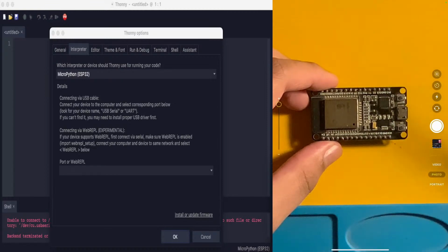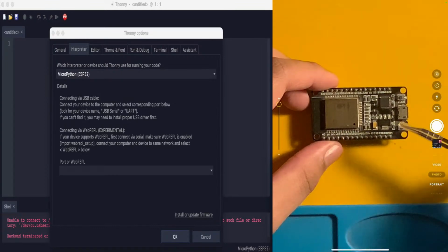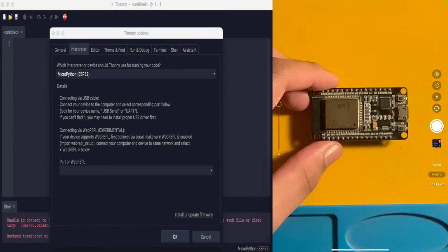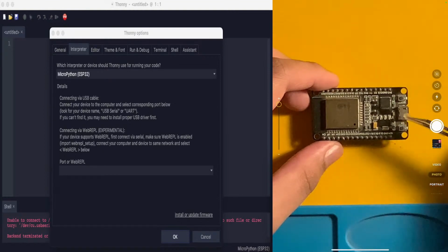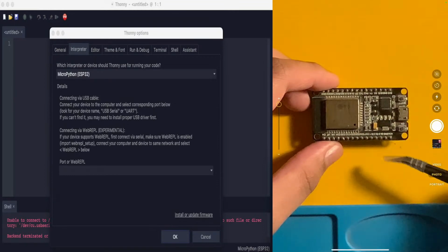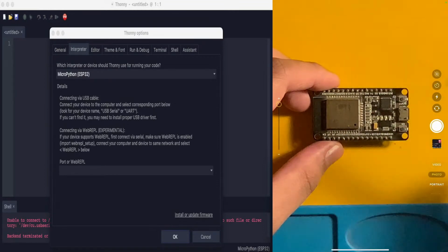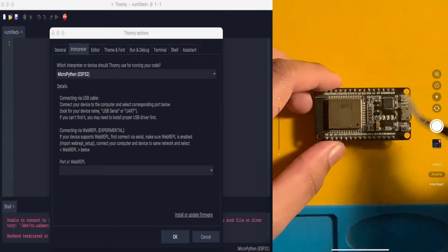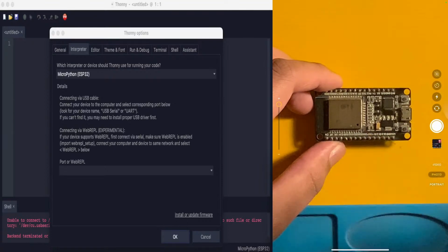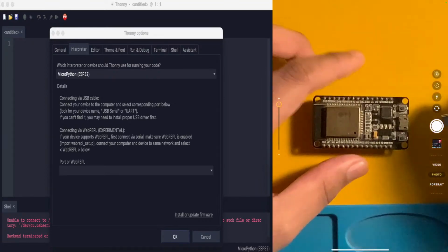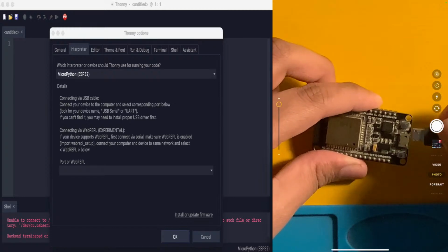Why do we need a voltage regulator, if you ask? We saw in the ESP32 pinout that it was running on 3.3 volts, but your generic USB ports from desktops and laptops output 5 volts. So to convert from 5 volts to 3.3 volts, we need a voltage regulator. Then we have some capacitors and diodes, all of which are protection components. General electric circuits need protection from, let's say, you giving more than 5 volts and all that. That is required for those things. Then we have two LEDs. Let me power it on, and you'll see the red LED switch on.